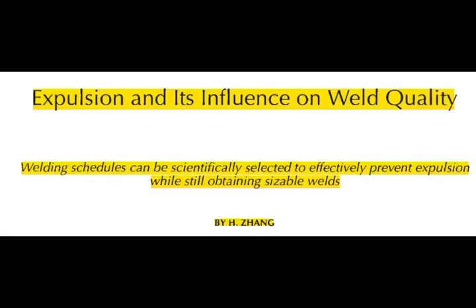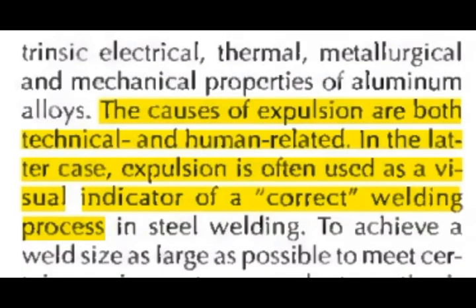Expulsion and its influence on weld quality. Welding schedules can be scientifically selected to effectively prevent expulsion while still obtaining sizable welds. The causes of expulsion are both technical and human-related. In the latter case, expulsion is often used as a visual indicator of a correct welding process.